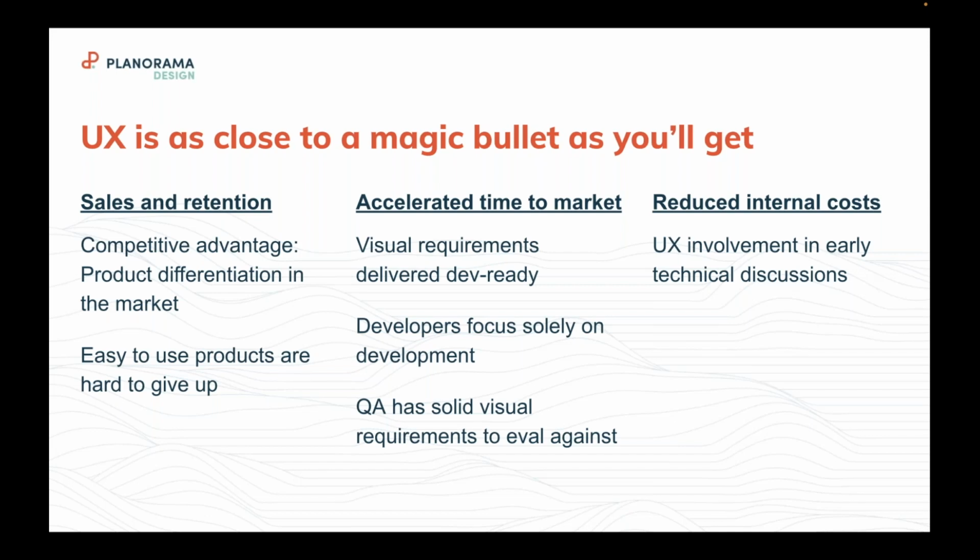There are all kinds of things that can happen with hardware or robotics, with physical movement. The encoders may be off, sensors may be giving you errant information, or sensors may be giving you correct information, and you have to deal with it in a certain way. All these different types of synchronous and asynchronous events, the software needs to deal with at some point. Designing the software purposefully to manage that is a non-trivial task. It's not something that should be an afterthought.